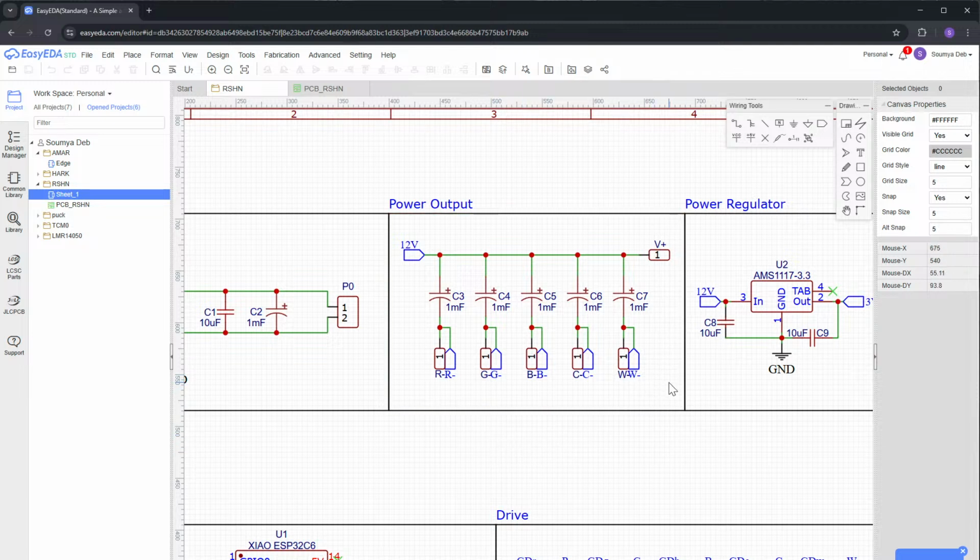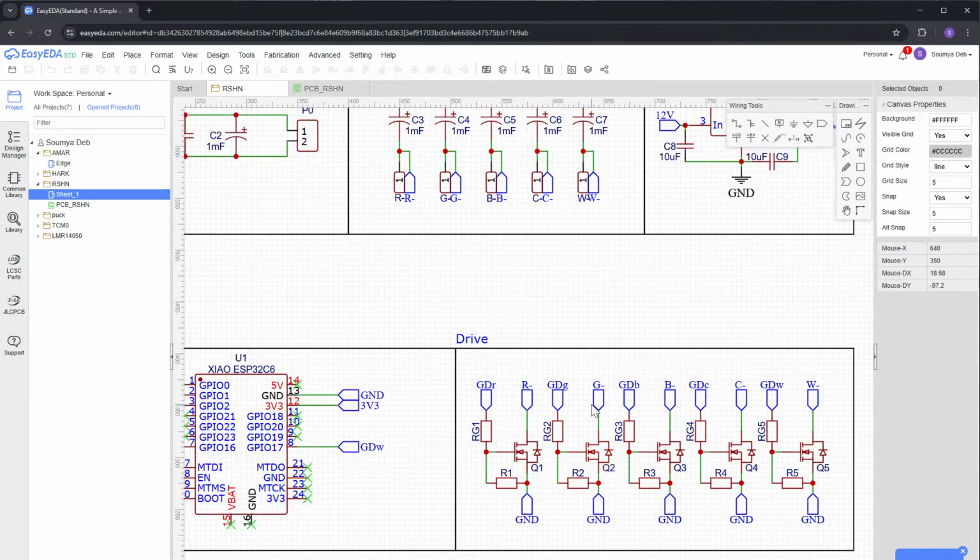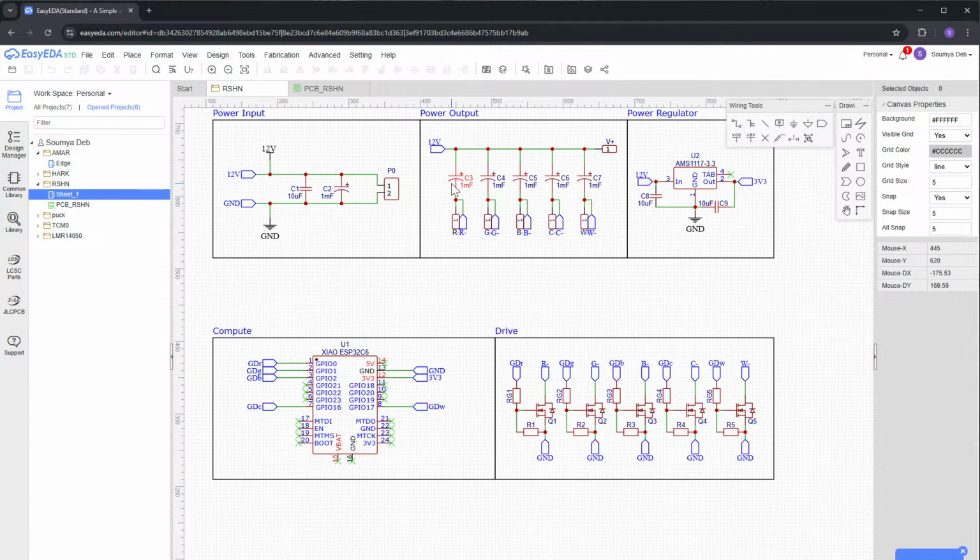That is doable. However, these big, huge capacitors here make it really problematic for the dimming to work properly, because they charge up faster: the MOSFETs open up faster and provide enough current to charge up this capacitor.